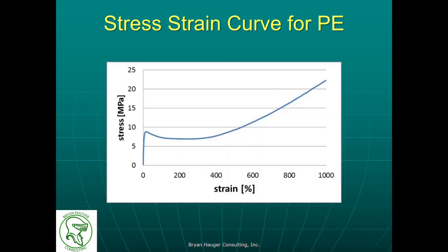Here you see a full stress-strain curve to rupture for an actual higher performance pressure pipe grade of polyethylene. We see that following yield, the region of drawing is at first stable as the necked region of the gauge continues to elongate under load. Eventually, a long fiber-like section can extend over the majority of the gauge until a strain hardening limit is reached. At this point, load once again rises rapidly with displacement and eventually terminates in the test specimen breaking.